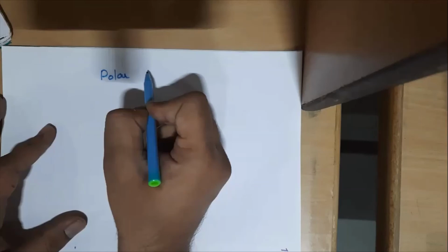Fine. So especially while dealing with noise, one must know the frequency domain behavior of the system, because if you know how it responds to the noise, then you can find some controller to reduce the effect of noise. Making something to overcome the effect of noise is related to sensitivity. If you are interested, I have already given slides, you can explore. With that, we can even take care of the sensitivity of the system also. So that is the reason for going to frequency domain behavior.